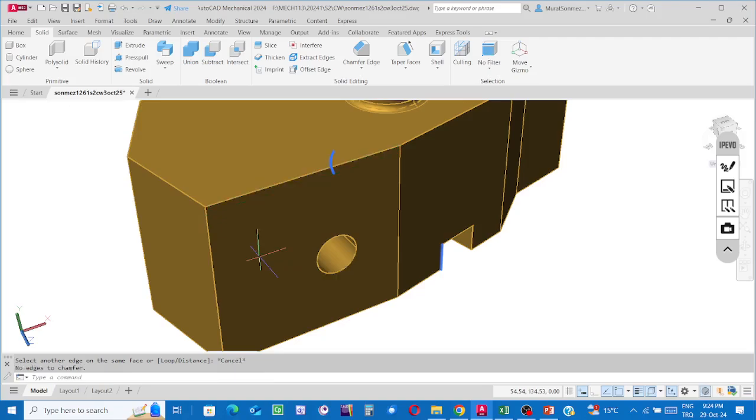Press the escape button, cancel this attempt, and then repeat the chamfering process. Okay, down direction key, select the distance option. First distance: I see that AutoCAD measured the first distance over this smaller surface. So the first distance is 6. Press enter.